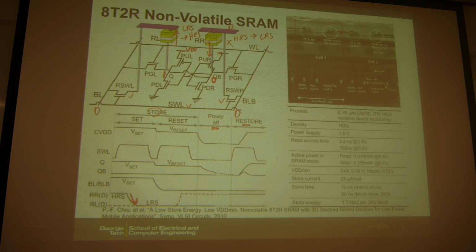The second concern is what you mentioned, the endurance, but that is not for the normal operation. That is for how often you power down your chip. RRAM has limited endurance, maybe tens of thousands of cycles. That is a limit on how often you can power down your chip, depending on how frequently you do this power gating, right? This also depends on your application. If you power down every microsecond, then after let's say a few hours, you cannot use this mode anymore, because the RRAM may be totally broken down.